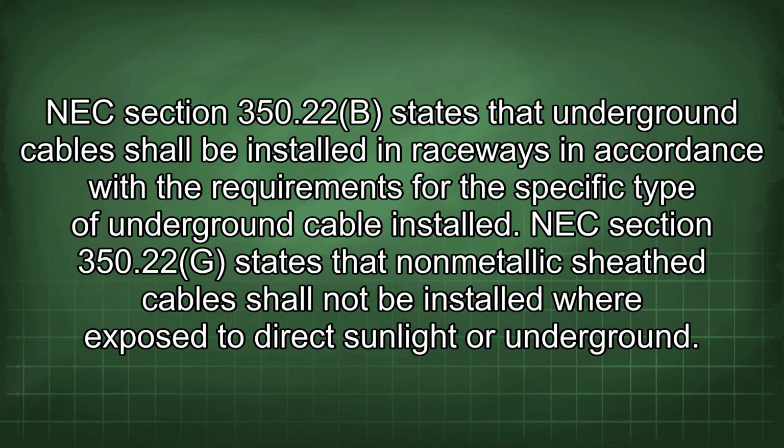NEC Section 350.22b states that underground cables shall be installed in raceways in accordance with the requirements for the specific type of underground cable installed. NEC Section 350.22g states that non-metallic sheath cables shall not be installed where exposed to direct sunlight or underground.